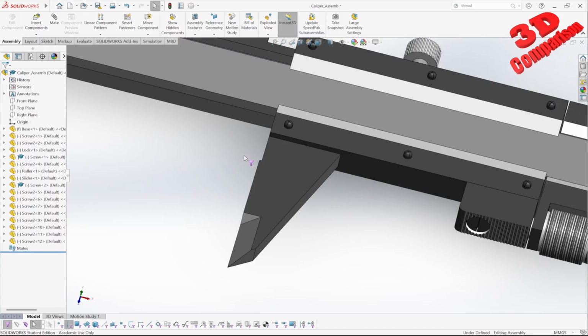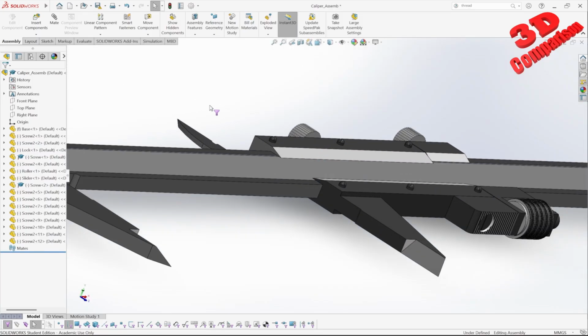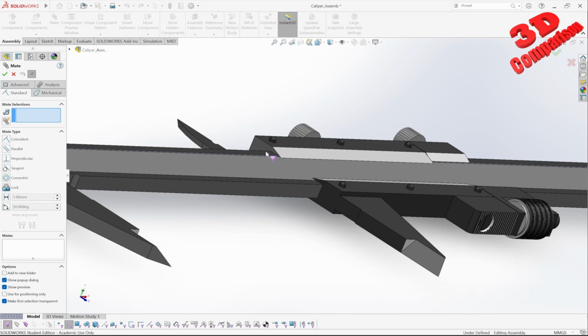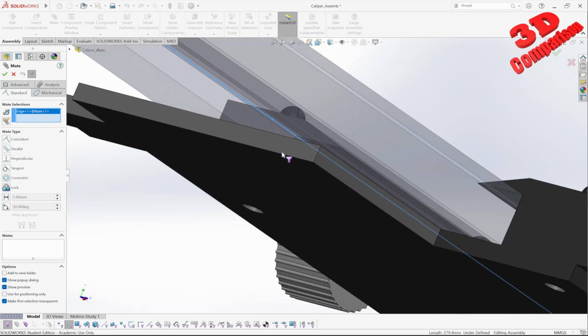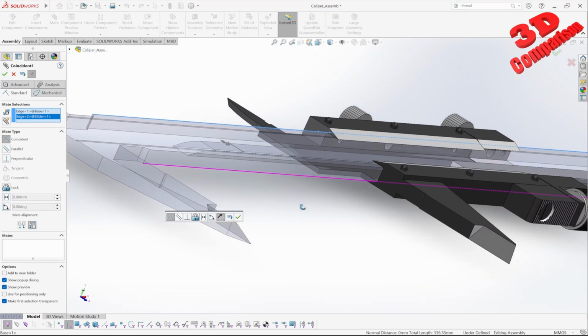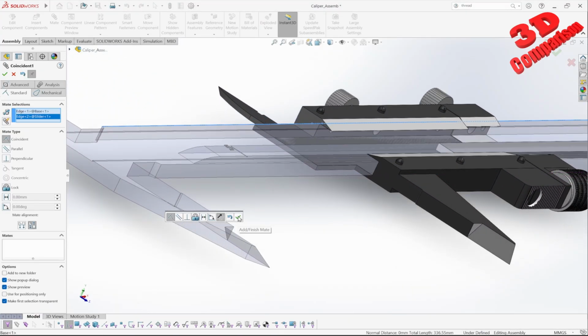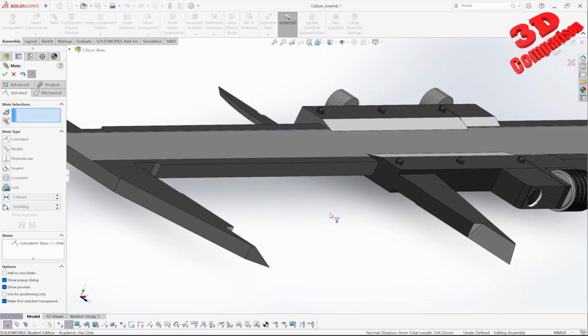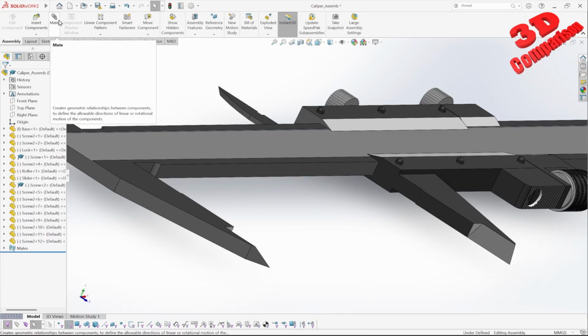V will be vertices. So if I press E, now you can see that I can only select edges. In some cases, if you want to do a mating over here, maybe that can help you. So I can start the mating and I want to mate that edge. And in this case, I can only select edges since I have that filter. And I can select those two, which will be the matching ones. That can be good. So usually this is why E is that filter, but I would maybe prefer to have a hotkey for mating because this doesn't have any. And in this case, we see that that helped us.